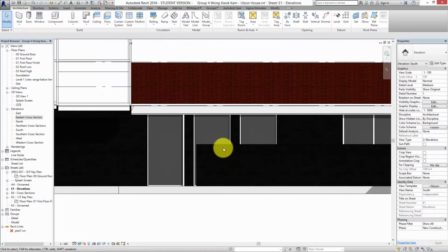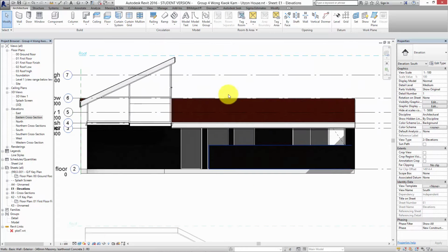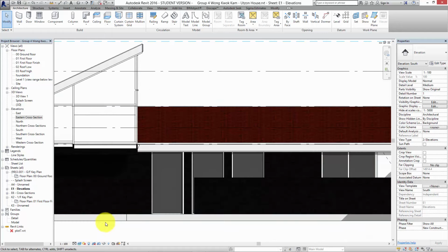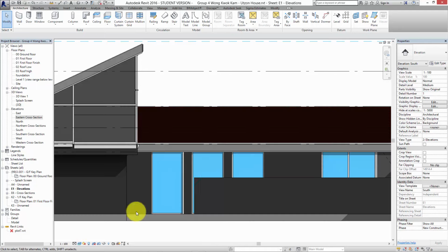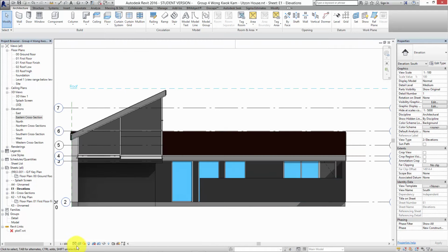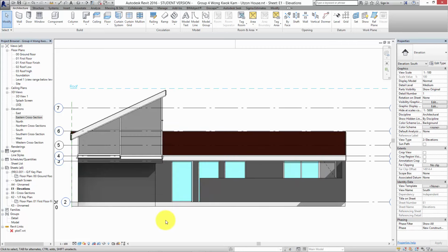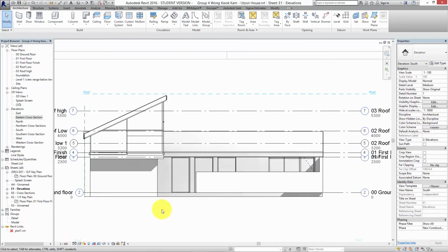The black material you're using is difficult to represent in this way, so I would probably change it from realistic view to either consistent colors, which is still a bit gray, or shaded. I would try and work that up a little bit as to how that's represented in that view. It doesn't necessarily have to be gray, or you can always just do it hidden line, I suppose, because if you have some quality in these drawings and some depth in them, you're still telling them something.